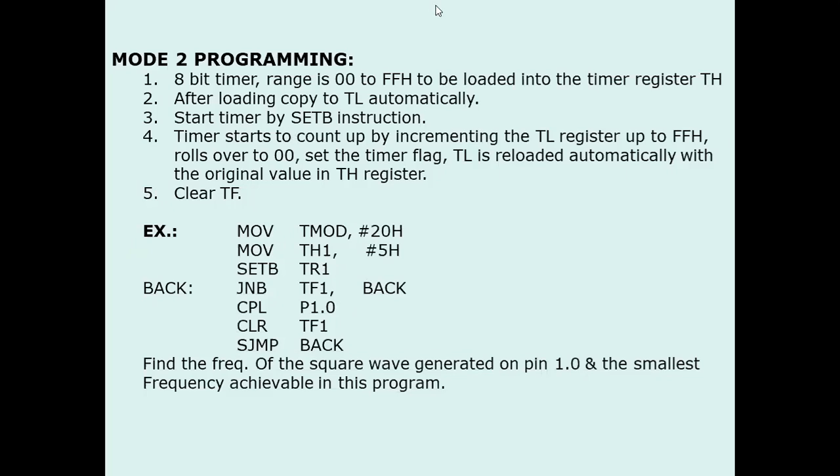Sir, mode 2. Mode 2, that is the thing. It is written over here, but still you were not responding. So here TMOD is loaded with 20H, and MOV TH1 with 05H, and SETB TR1.